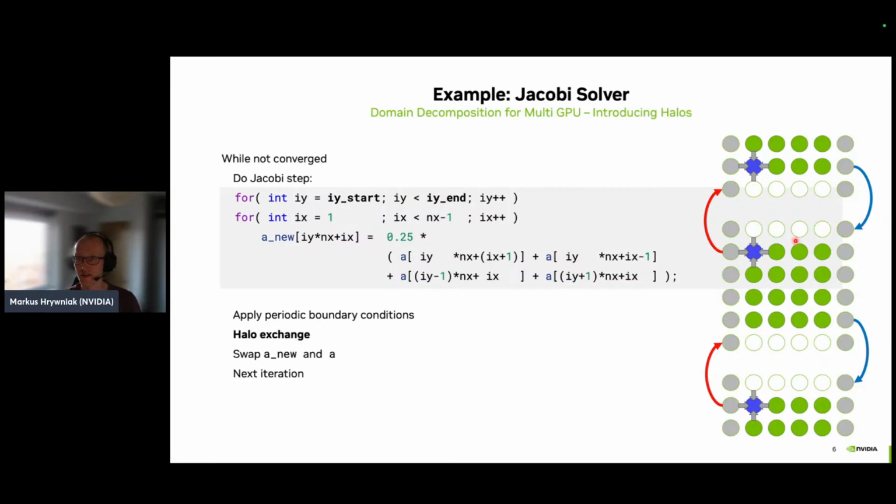So the global domain is really much larger than the local simulation domain. But we also run into some complication, because if you look at this blue dot here, it still needs the value above, but the value above is now no longer computed locally. The value above is actually computed here. And so that means we need to exchange data between neighbors along these boundaries.